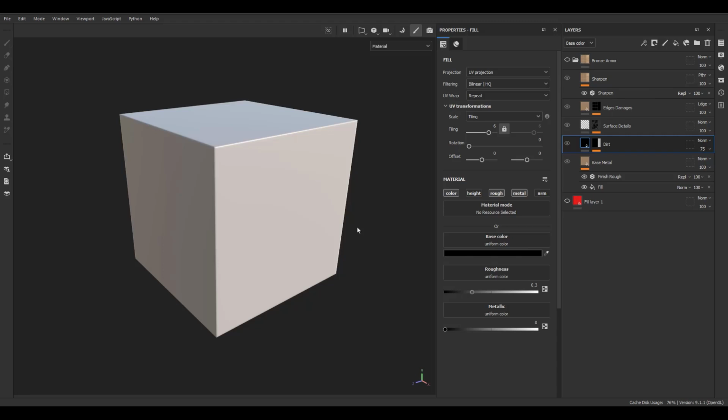And for the second technique, we just put seams for the UV on the sharp edges of the model. In this way, we can control these artifacts on our mesh maps.